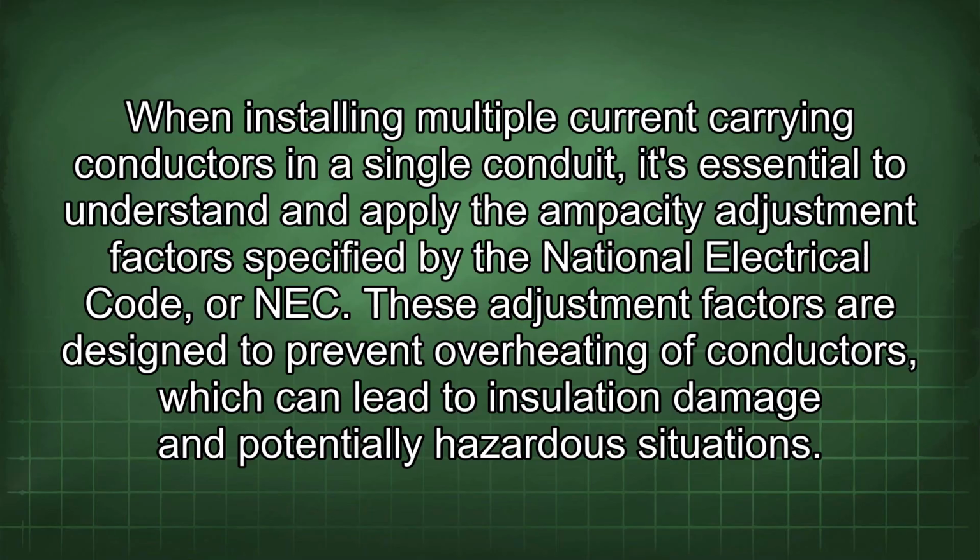When installing multiple current-carrying conductors in a single conduit, it's essential to understand and apply the ampacity adjustment factors specified by the National Electrical Code, or NEC. These adjustment factors are designed to prevent overheating of conductors, which can lead to insulation damage and potentially hazardous situations.